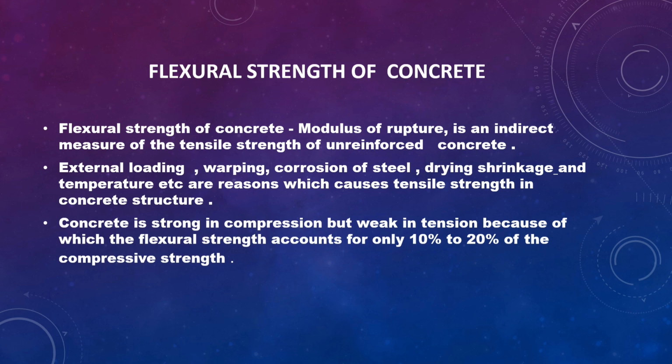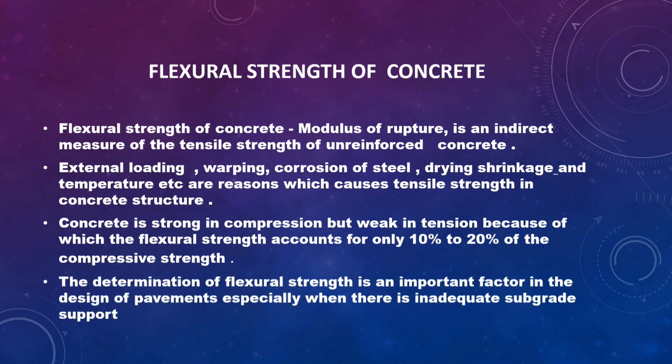Concrete is strong in compression, but it is very weak in tension, because of which the flexural strength accounts for only 10 to 20% of the compressive strength. The determination of flexural strength is an important factor in the design of pavements, especially when there is inadequate subgrade support.